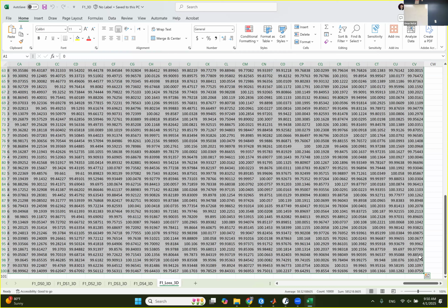If you multiply the number from this table right away with the building replacement cost, you have to divide by 100 because these values are out of 100. So 50 over 100 gives you the percentage. Because if you multiply 100 by 500,000, that is going to give you 500 million. That's why I divide by 100 when I calculate the losses.